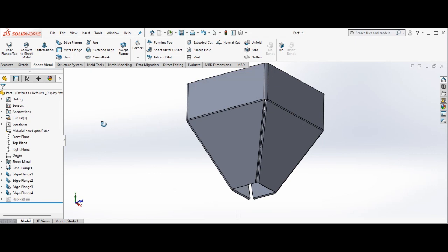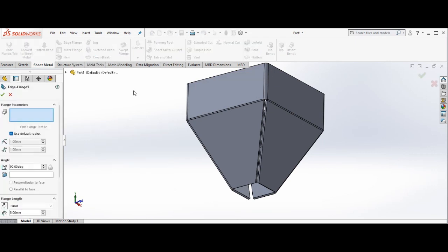We right click, click select, go to edge flange. Click on this position, draw to a particular direction. It's 5 mm. Let's draw outside here. 5 mm, make it 25 mm. You can see it's 25 mm here.